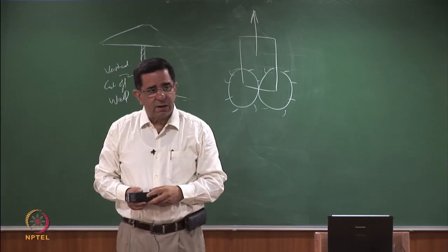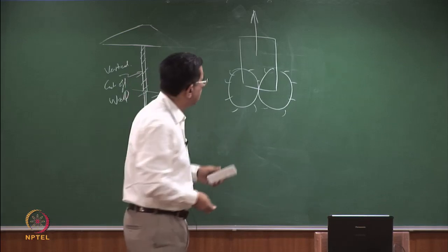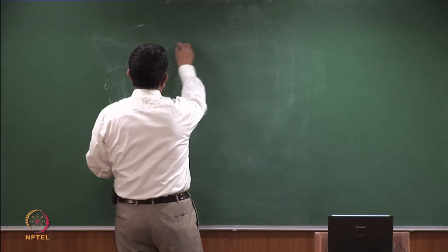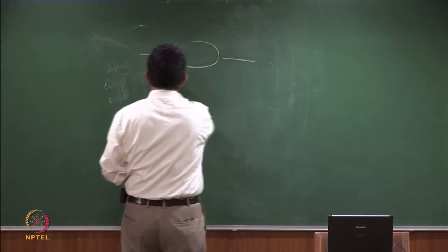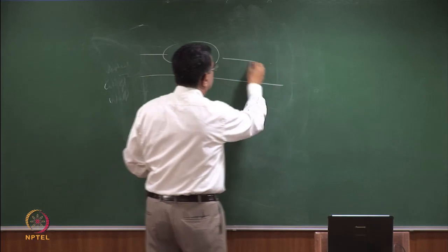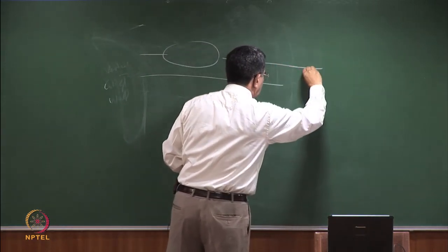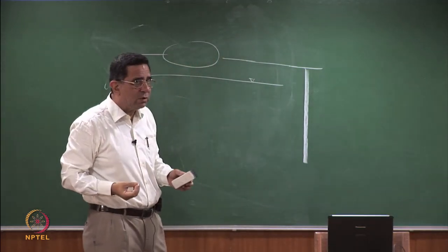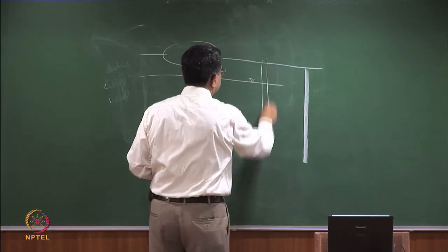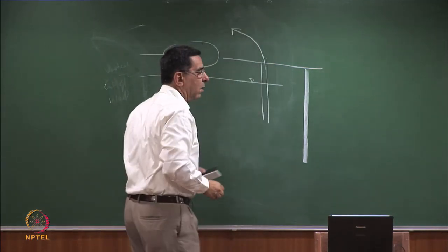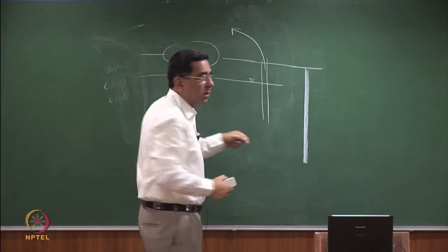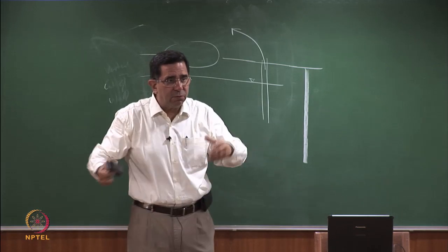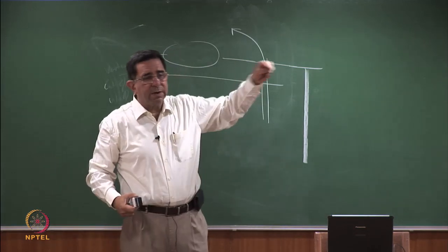Subsurface drainage, right. On this side we have some, okay. So there is a waste, there is a contaminated plume. My traditional solution is, let me put a cutoff wall here. We have to do something to this contaminated water. I can do two things. I can do pump and treat, or I can make a continuous pervious trench around it. If you put pump and treat, you have to put the pumps at very close locations in plan, say a few meters away. You can take out the water, treat it and re-inject it.